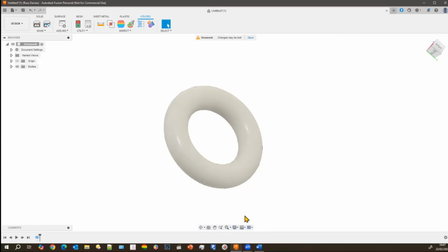If you want to edit something of that nature, then really doing it in Fusion is hopeless. You should be using something like Blender. Really, I think STL files in Fusion, you need to have fairly tidy, what I would call mechanical parts rather than figures and animals, because the curves you'll have trouble with. So how do we go about?